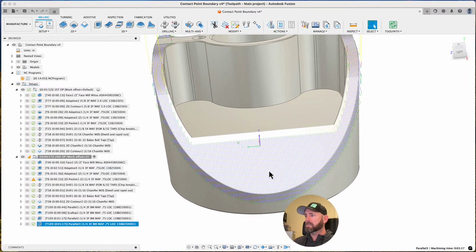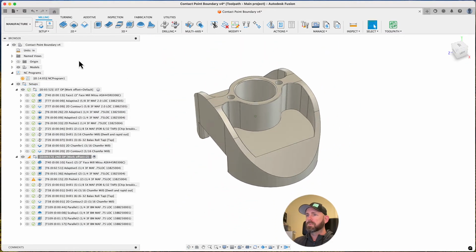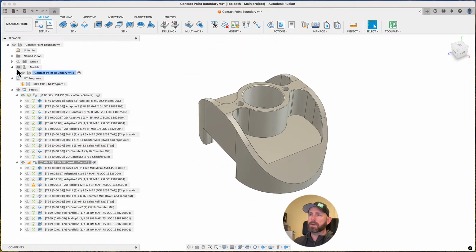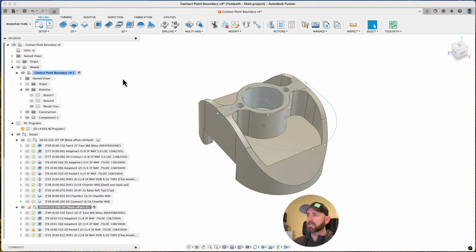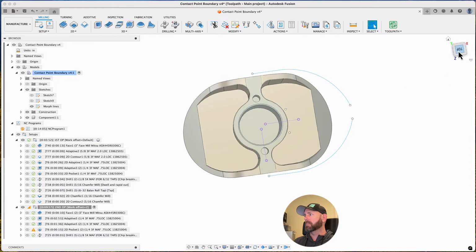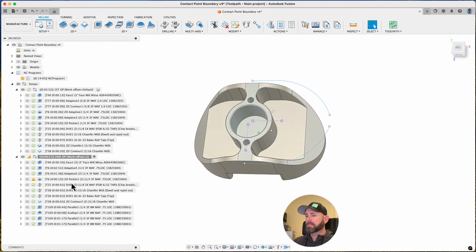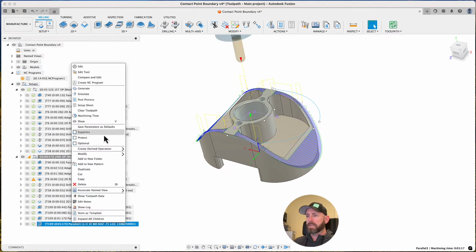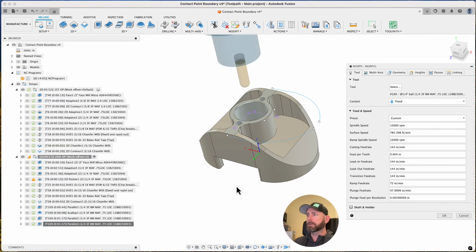Cosmetically, what I'd like this part to do different or better is accentuate this kind of sweep motion here. So I'm going to use a morph and then we'll wrap it up. Ahead of time, I went and created this sketch. I just want to bend and manipulate my toolpath based on a sketch. So I'm going to turn that on, and then come to this toolpath and go Create Derived, 3D, and Morph toolpath right there.